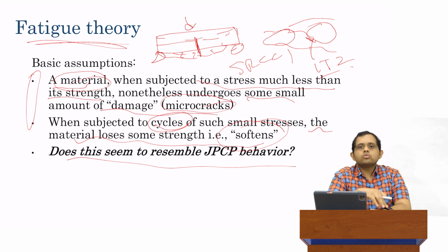So, although I'm giving you the assumptions of fatigue theory, and I'll already tell you we use fatigue theory to analyze JPCP, you should not blindly assume that's correct. So, let's see. The first assumption says that when the material is subjected to stress, which is much less than the strength, these micro cracks develop.